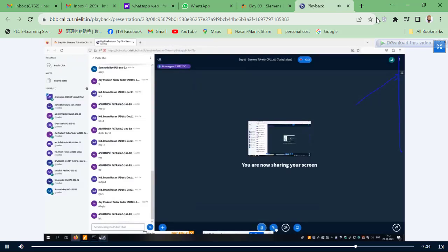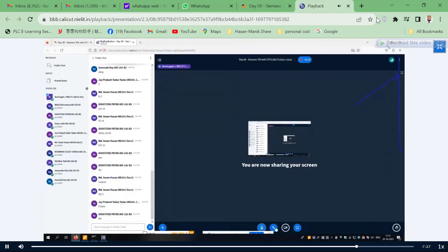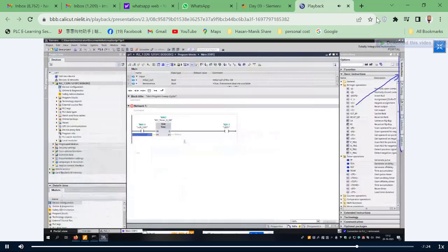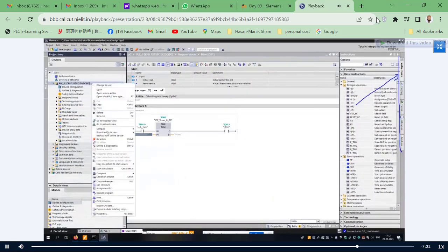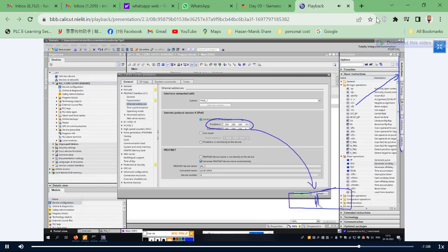Okay. So one problem is that you see, while downloading, I already told you about that IP address, right? You see this IP address. Minimize. Go to the process. This IP address we assigned while creating this project. So for example, how can we assign this information to a new PLC? All PLCs have a MAC address. Yesterday also I told you, the media access control address is a fixed one. Based on this, it will work, and here some option is there.